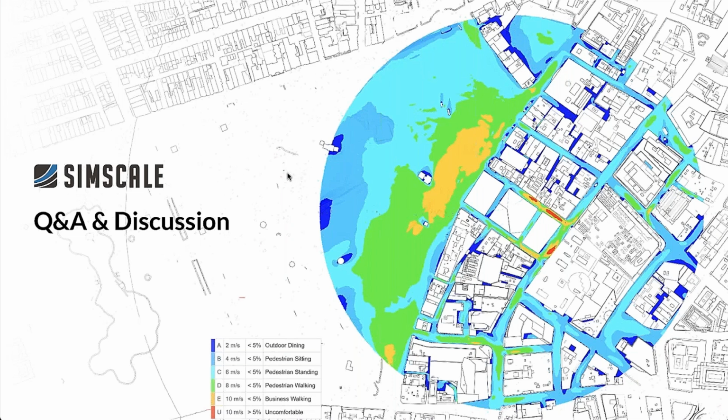Let's take some technical questions first, and then we'll move on to the industry level ones. Darren, you showed a slide just at the end there about CHT where it had PMV, PPD, operative temperature, various other bits that were involved. Would solar be included in that? Calculating solar gains, would that be connected to the AI side eventually or now? Yes, correct me if I'm wrong, Rickard, but it's currently enabled, so it's included in our radiation modeling, and that means the MRT field as well.